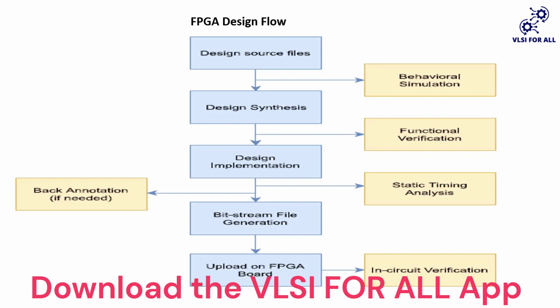Whatever FPGA we are using, we choose the FPGA kit in the initial stage, like Virtex, Artix, or Kintex, whichever FPGA board we are using. The bitstream file should be readable according to our board, so the bitstream file is most important. Only after the final bitstream is generated can we deploy it on the FPGA kit for testing. So this is the whole process of the FPGA design flow.